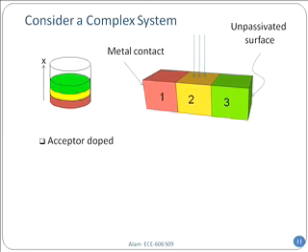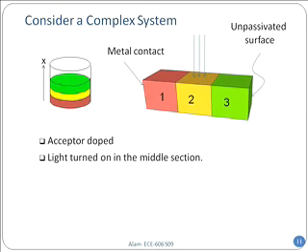So the first thing it says, I'm solving a problem, let's say it's an exam problem, that it is acceptor doped. So you immediately in your head realize that this is essentially all acceptors, and p, the number of holes in the extrinsic region, is equal to Na, right? That's the first thing you immediately realize as soon as you hear the word acceptor doped.